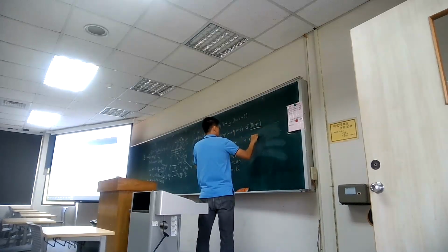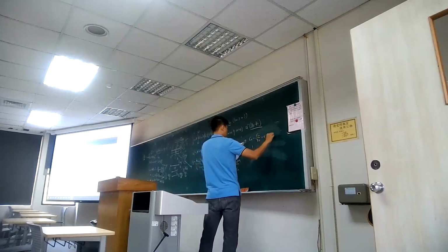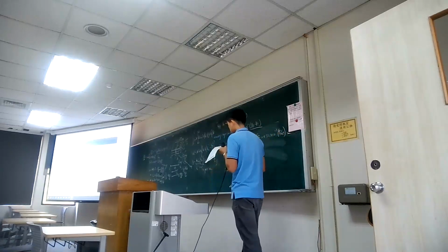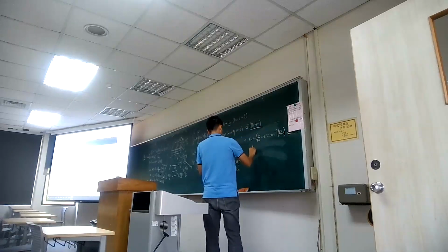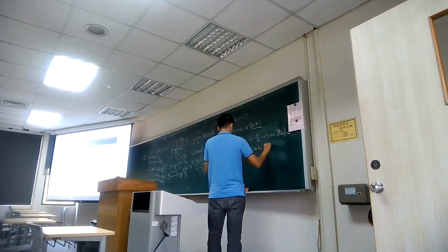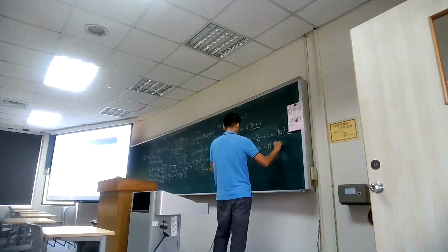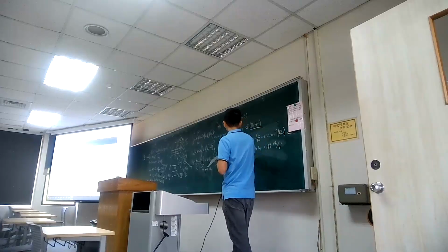Based on this, that will be simple, because you already have the C_ox, which is epsilon_ox over t_ox. That will give you something like 4.3 multiplied with 10 to the minus 3 F/m². If you get the K_n', that is μ_n C_ox, which equals 194 micro A/V².